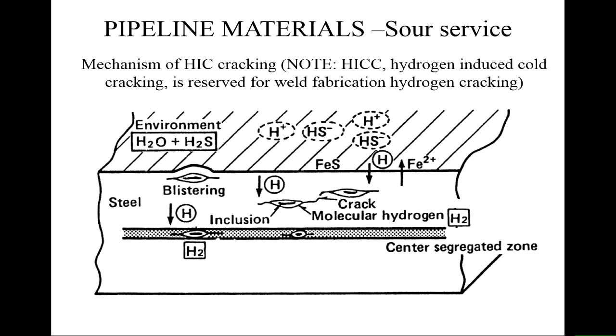And the reason for that is it's very difficult to analyse how much hydrogen is present in a material and analyse whether hydrogen is the cause or not. Detecting hydrogen is difficult by most modern methods. So because you can't analyse for it, you can't prove it is or it isn't, it tends to be the default explanation for things you don't understand. So I'm sure not every failure is due to hydrogen embrittlement, but since we can't measure the hydrogen, it's as good an explanation as any for failures we can't understand.